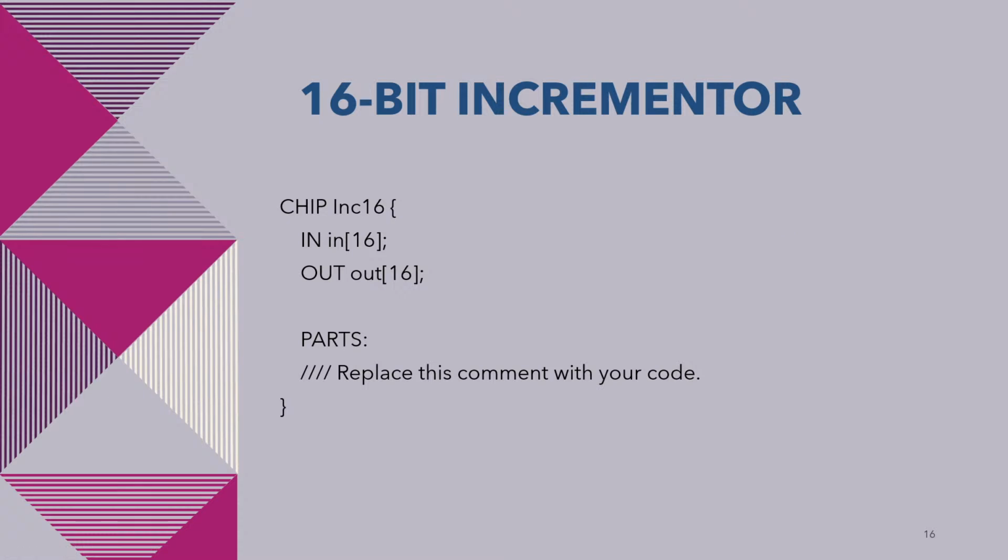The 16-bit incrementer takes your 16-bit adder, and it makes a simple counter for you. Basically, you take the 16-bit adder, put some loopback logic in there so that the last output will be the input for the adder if there is no external input. Let me think about that for a moment.